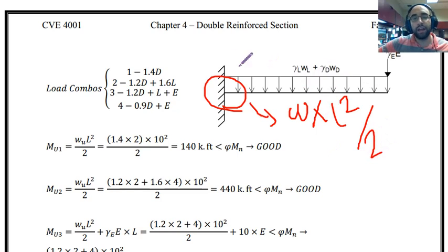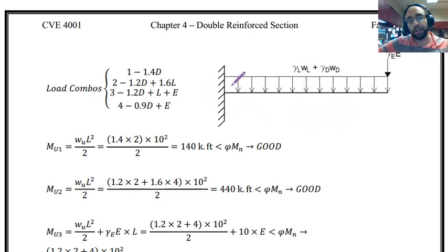That is not difficult. We have just a distributed load, we can put a concentrated load because of this distributed load, and that is the area under the load that will be at the centroid of the uniform load, and then multiply by the distance to the end of the beam, that will be the moment at the end. These are just statics and structural analysis. You are already familiar with this.